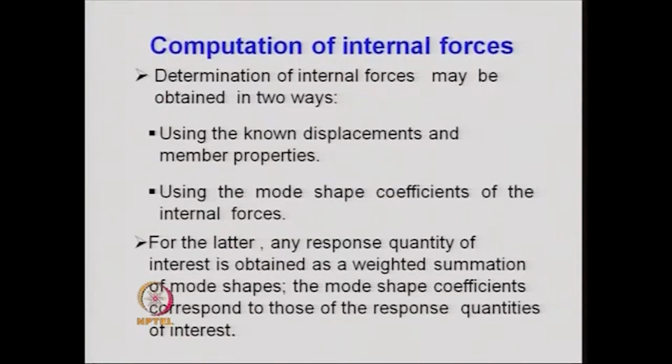If one has to calculate the internal forces, or the bending moment, shear force, etc., then one has to take into consideration a higher number of modes. If we use the mode acceleration approach, then for any response quantity of interest, we can obtain a better estimate of the response quantities by using fewer modes.